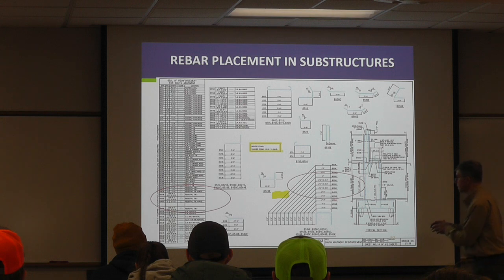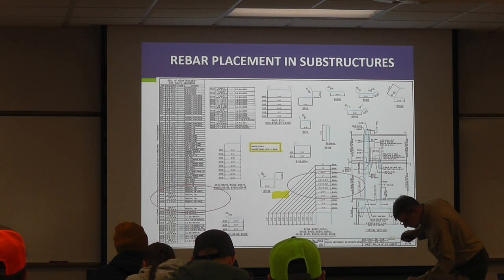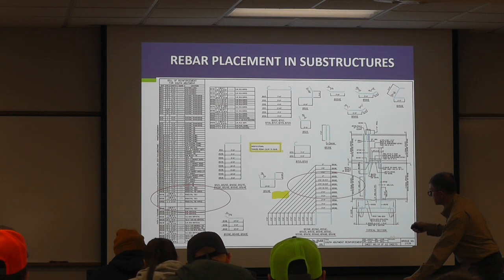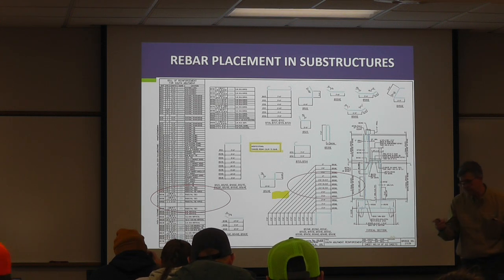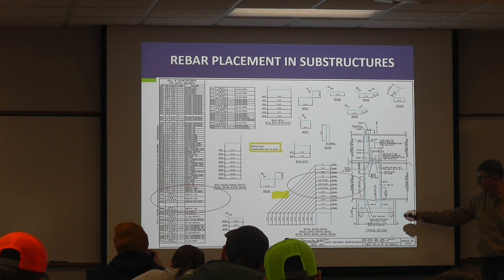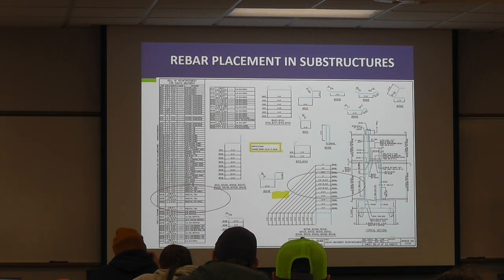Oh, it's just I can't read, that's why. 2 foot 1. 554, okay, 554 is this one. That's what I can't read. Okay, 2 foot 1 to 3 foot 5. So that means that dimension, the first bar in the series is 2 foot 1. The last bar in that series is 3 foot 5. Each one has the same leg distance if we take this down and whatever that one is. That leg is the same.